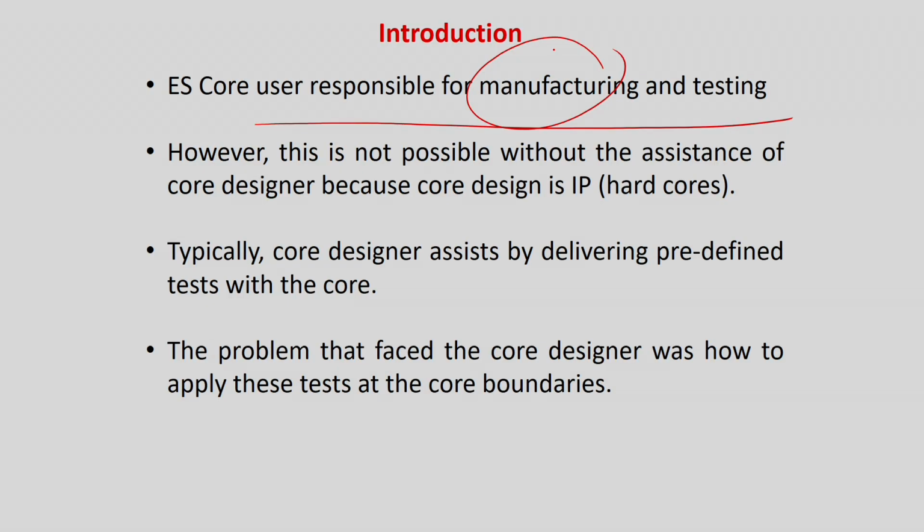However, this is not possible without the assistance of the core designer, because the core design is IP. So therefore you have just sold me a black box. I have to test the internals, but you are not going to tell me the internals. So what I can do, I have to take your help. Obviously, as you have designed it, you will not tell me the internal details, but you will at least tell me to apply these patterns and everything will be tested. So those things you will give to me as the test patterns.